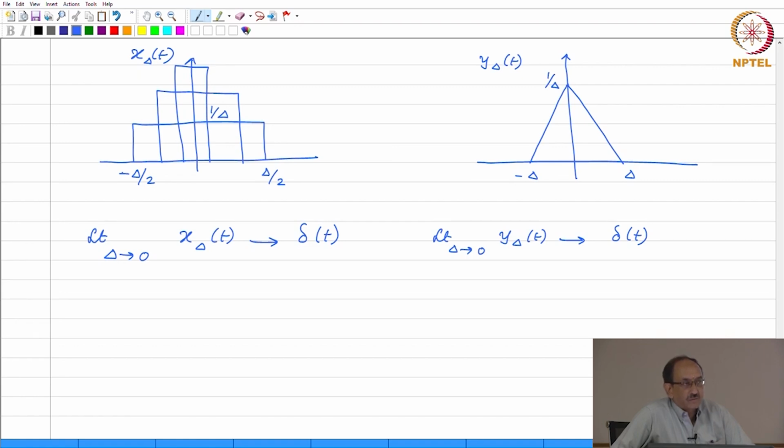If the pulse width becomes larger and larger, in the limit the pulse becomes the what signal? No, the pulse becomes the single rectangular pulse. If the width becomes larger and larger, it becomes the DC function, and its transform must be the impulse. Therefore, you have a sinc in the transform domain that is going to become like an impulse, right. So, that is another function that becomes an impulse in the limit.